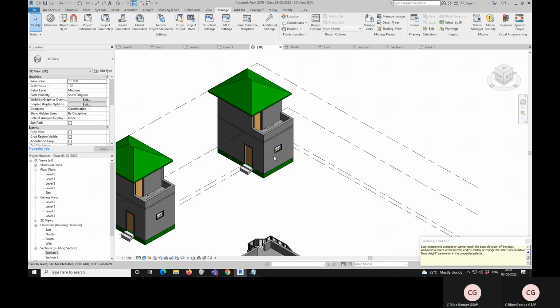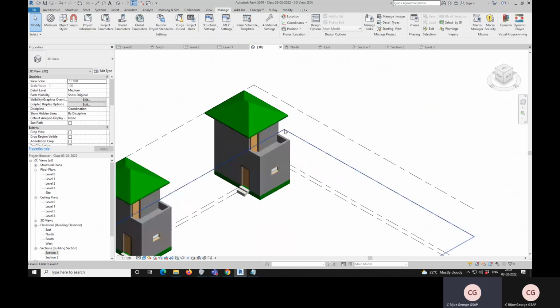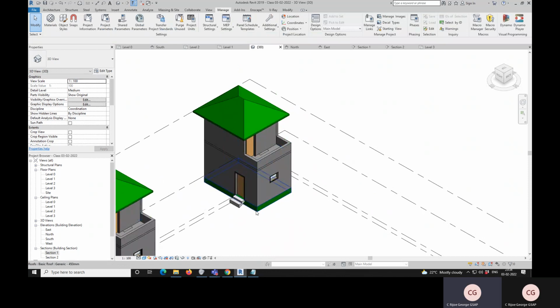And this itself is divided in two ways. One is creating materials and then applying them on a component level. The second one is creating a material and then applying it on a face level, on a side level. The component level means I create a material and apply it to a particular wall. You name a separate wall and create a material for that, and you apply the same wall wherever you want. That's component level. Another one is paint texture. Just paint it, just like how you paint a wall in reality, same way you paint it in 3D.